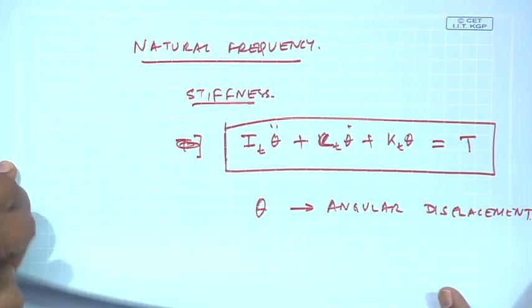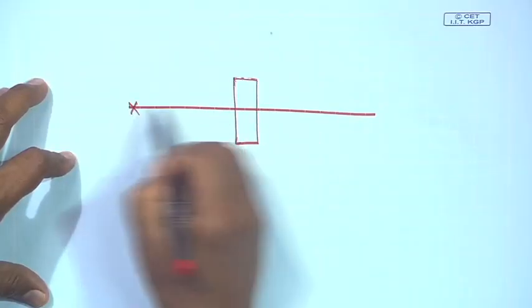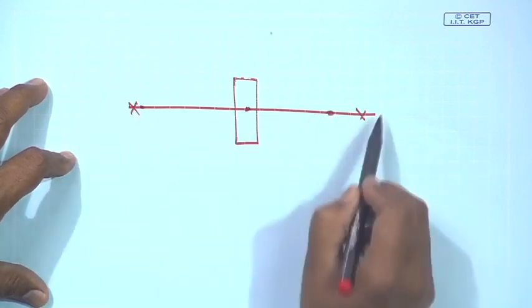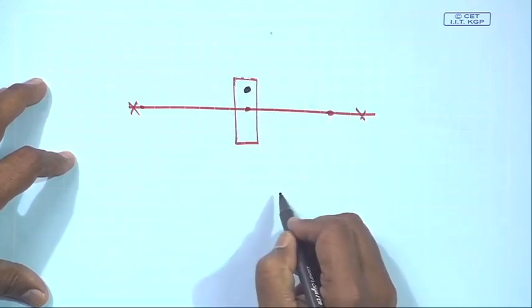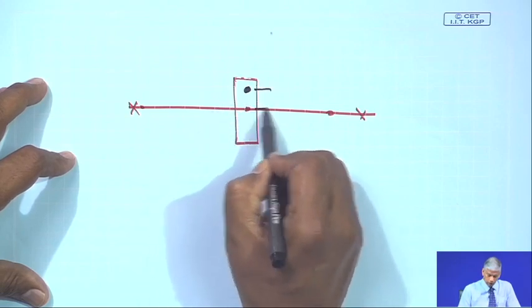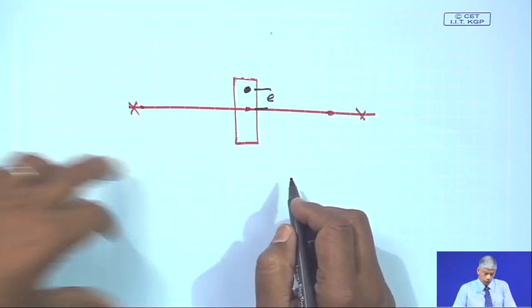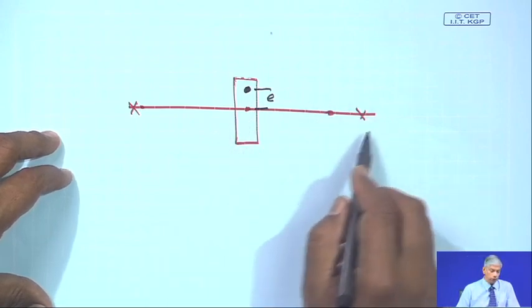And then many things happen in these shafts. We have assumed that this shaft is concentric between the two bearings. That means the geometric centers of all the systems are in the same line. Imagine if there was an unbalance or an eccentricity in this shaft, a geometric eccentricity E. What is going to happen to these displacements at certain speeds omega is again a factor which we need to study.